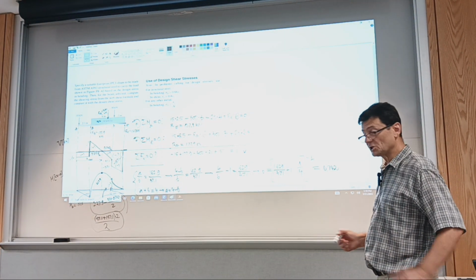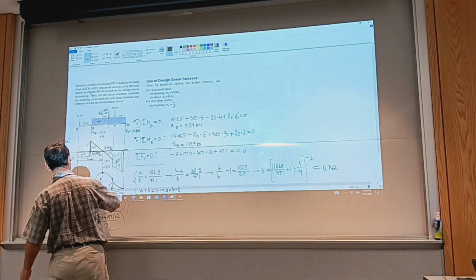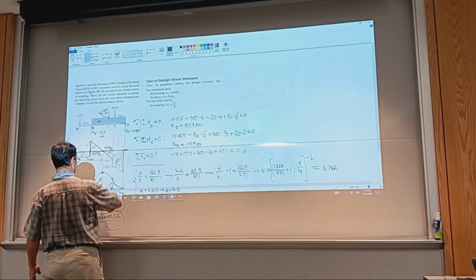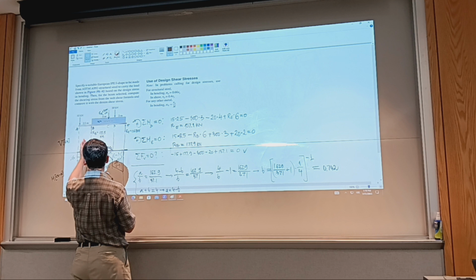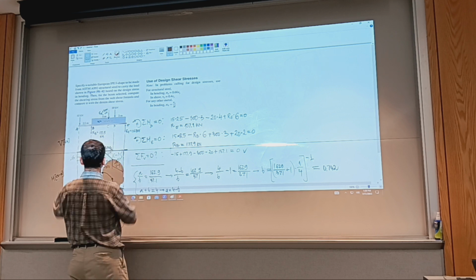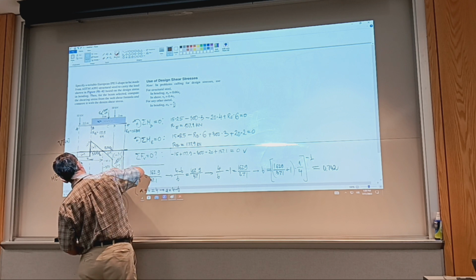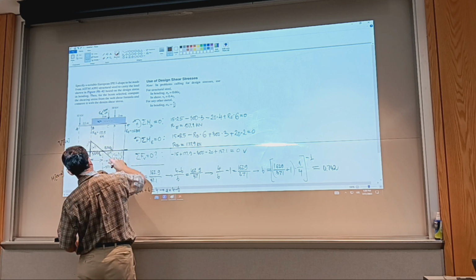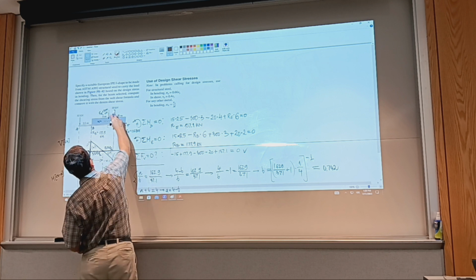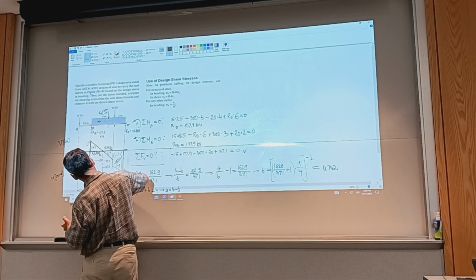All right. So it takes a little bit of an exercise looking at slopes. So it starts like here. I start with a positive slope that goes to 0, which is this point, and then I continue smoothly. Again, I'm on a parabola because of linear shear, and because of this drop caused by the 20K force, I have to change.